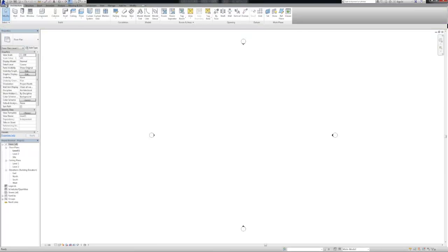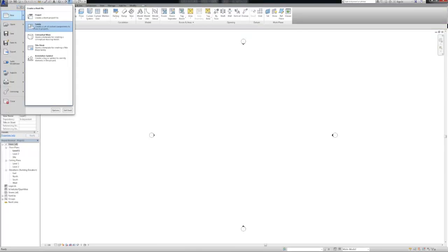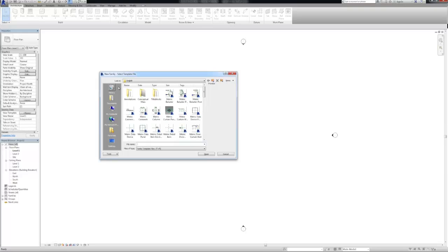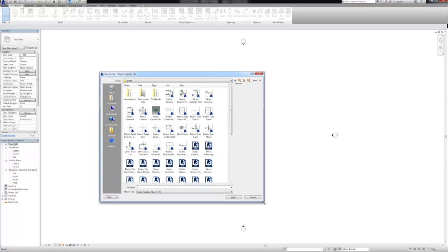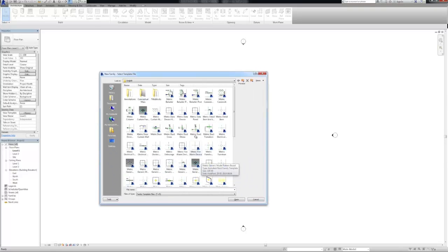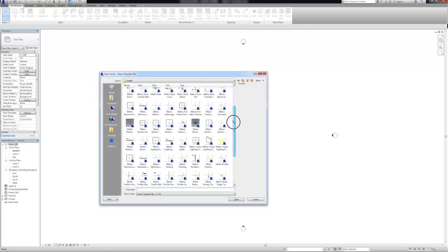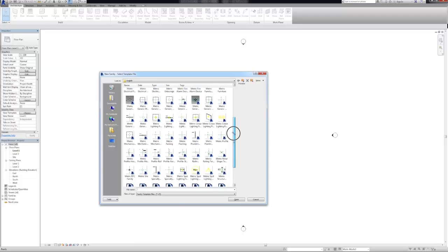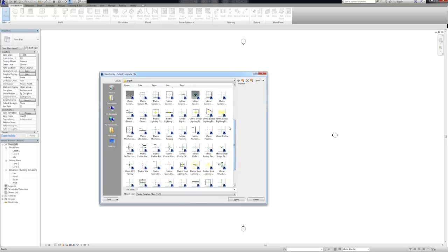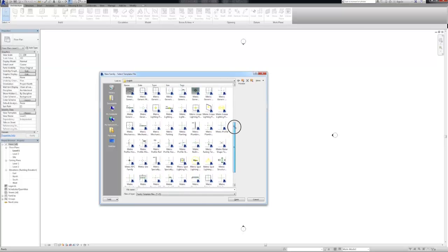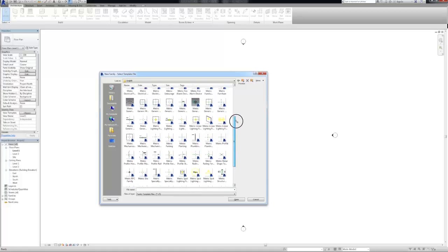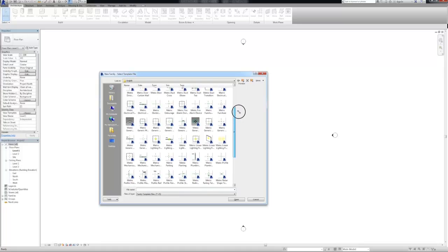Open the Revit menu and choose New Family. We'll start by choosing a template for this family from the Template section of the library. Every Revit family is based on a template that specifies the category for the family or any special hosting requirements. Most families can be placed anywhere in a project or model, but some families can be defined as being wall or ceiling hosted. Components from these families can only be placed in the appropriate hosting elements.